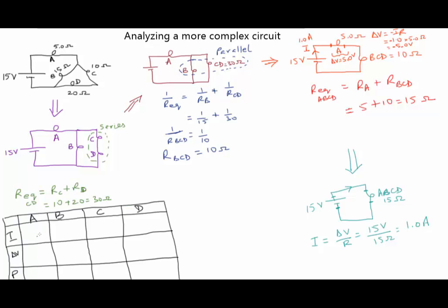So as we go along, I'm going to collect my final answers over here. We got the current through A already as 1 amp. We got the potential difference across bulb A as minus 5.0 volts, where the minus simply stands for the fact that it dropped in the direction of current. And the power was I times V, which we can write as minus 5.0 watts, simply to indicate that this power is consumed or dissipated by the bulb as opposed to being produced by it.